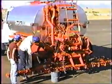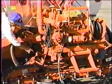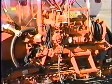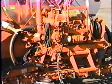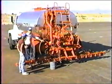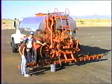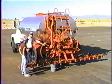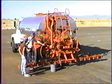Underneath the truck, on the rear end, the axle housing of the truck, is another sensor just exactly like that. And that's where we pick up the speed of the truck. We actually count the teeth on the ring gear, and that shows us the speed of the truck. Speed is important, gallons per minute is important. Those are all things that have to do with the spread rate that we're going to put down. We'll talk about that when we get back to the cab.